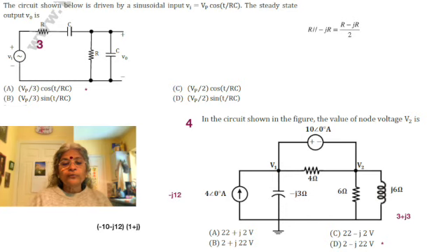Here, what all do we observe? We see first and foremost a current source and a voltage source. The current source is in parallel with minus j3. That's good. And the voltage source has a resistance across it, which we discard, because any impedance directly across a voltage source can be removed from analysis. We also see that 6 and j6 are in parallel, so immediately it comes to us that it is equal to 3 plus j3.